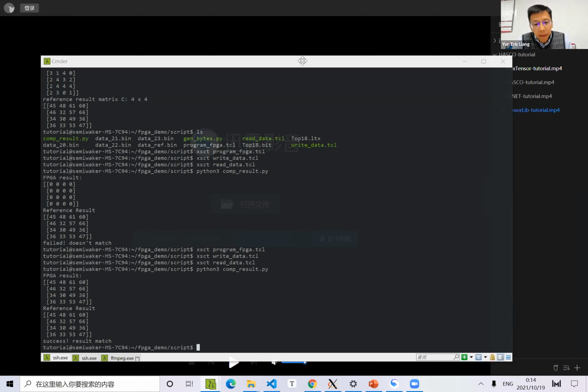The resource usage is due to how many DSPs we have used to show the frequency. If we use more DSP resources, the frequency can be slowed down because of routing constraints. So we can use about 75% DSP resources without degrading the frequency.